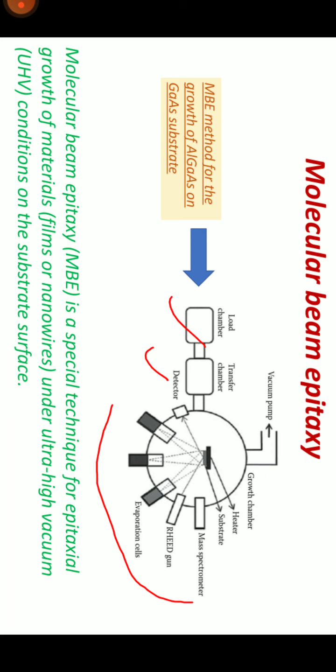The main attributes of molecular beam epitaxy are a low growth temperature, 550 degrees Celsius being required for gallium arsenide, that limits the diffusion and maintains the hyper abrupt interfaces, which are important in fabricating two-dimensional nanostructures. Then a slow growth rate ensures a well controlled two-dimensional growth, and a very smooth surface is achievable by this process and technique.